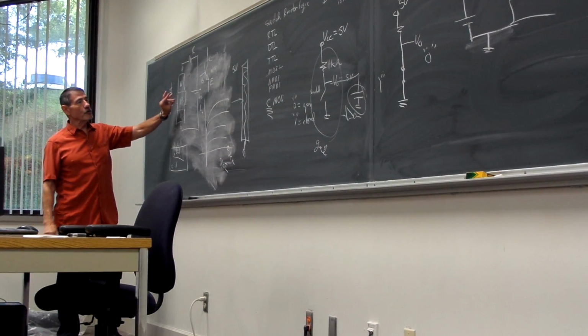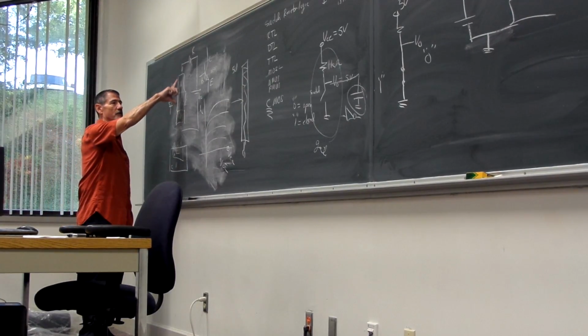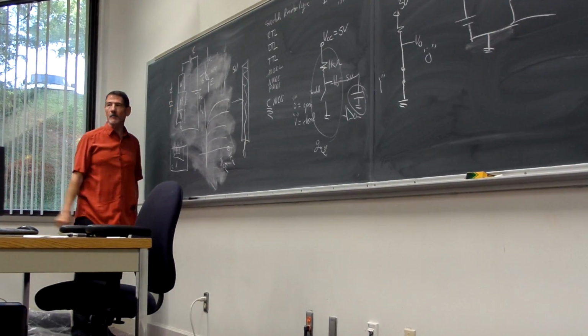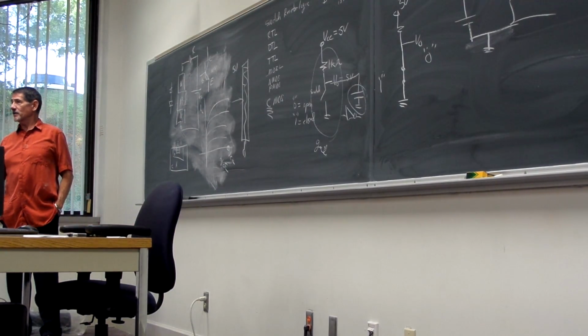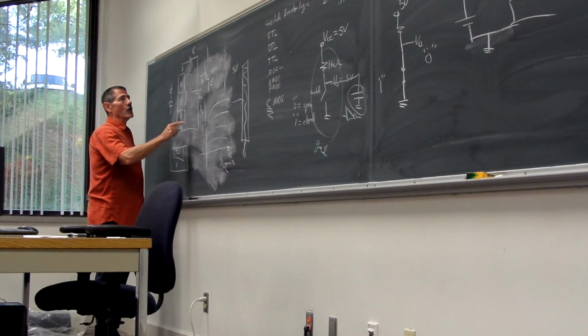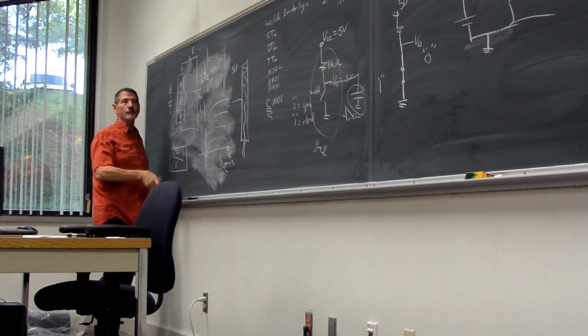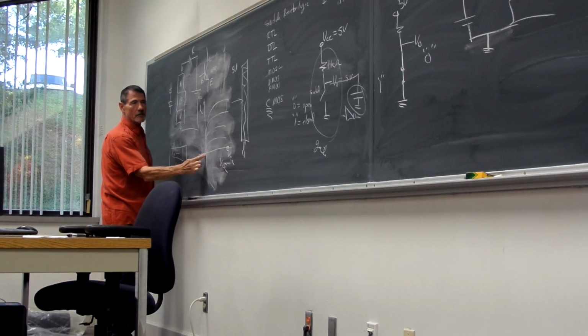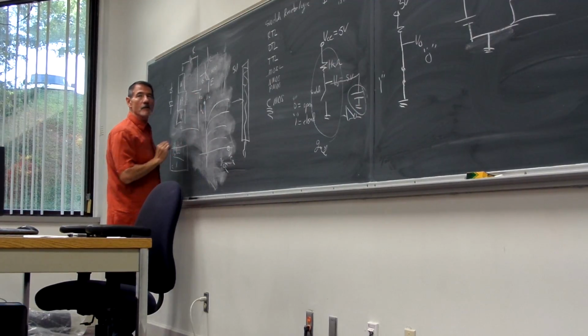If this guy were to go to absolutely zero, if we could dump enough current in there that we could drive this thing to 0 volts, actually we're only going to be able to drive it to about 0.2, 0.3. Somewhat depends upon the size of the transistor. Hockey puck size transistors have much larger saturation voltage, around 1 volt or so. Tiny transistors, 0.3. But assuming that we could drive this to 0, how much current would flow? So 0 collector to emitter voltage, how much current? VCC over R.